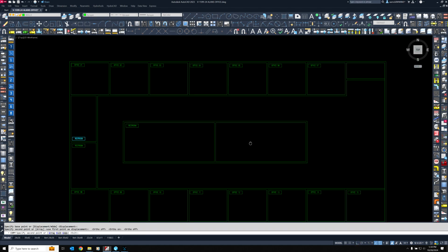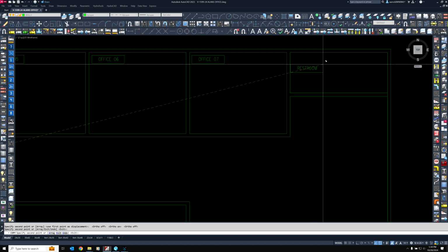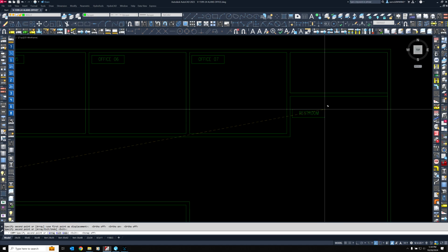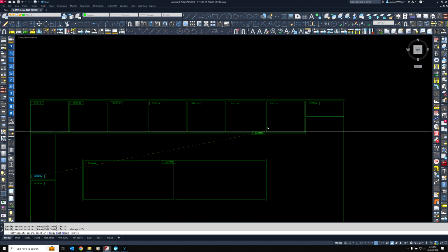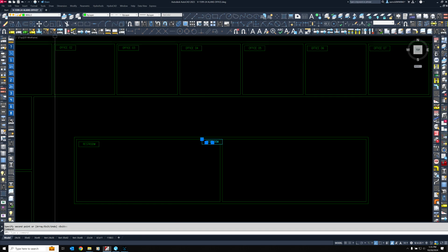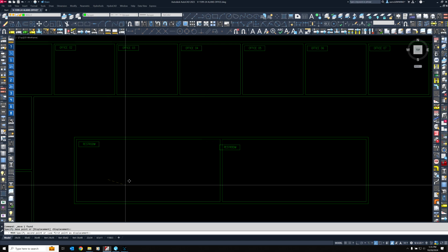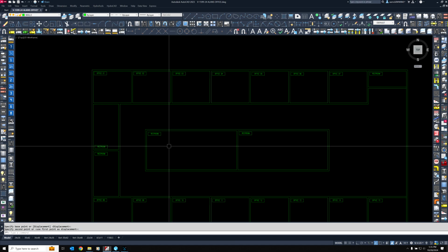All right, insert our conference room tags, and then we'll fix that, and then we'll rename it. Let's turn off our snaps. That'll keep that from happening now that I'm copying. So left click. Here's how you move things around. Pick anywhere you want. It'll always stay aligned, and we'll drop that in the corner.